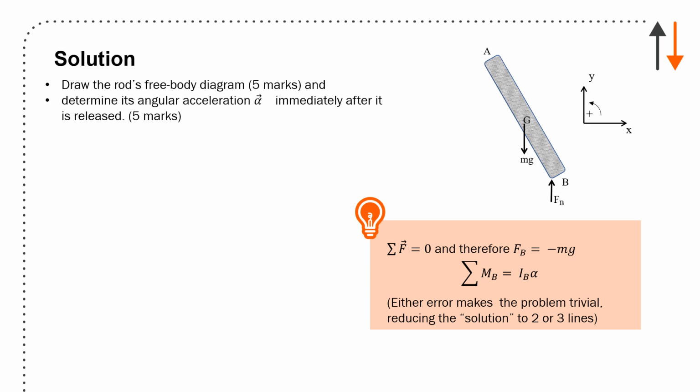You have the free body diagram right there because there's only one point of contact. This thing is only touching the ground here, so that's the force at B. You have weight acting downward, and those are the only two forces determining this.